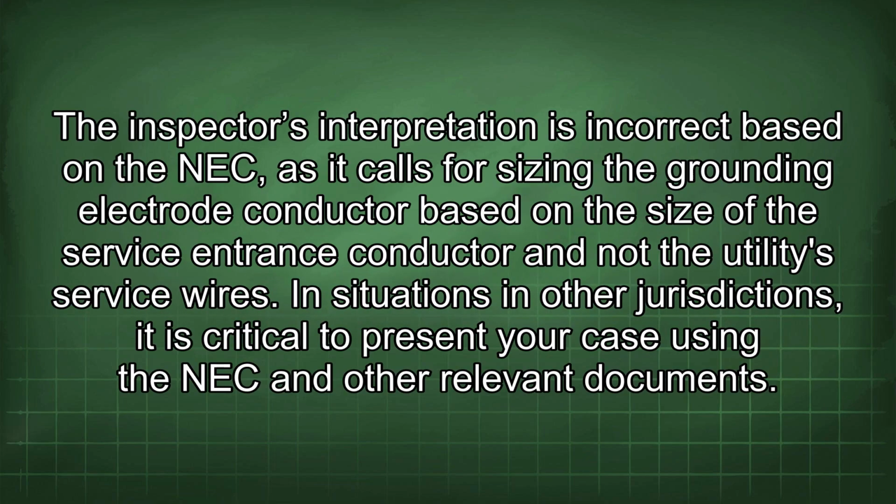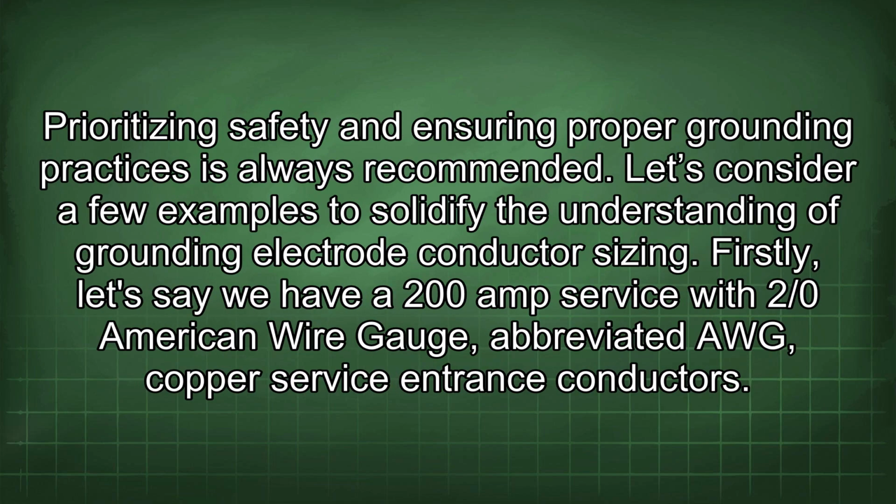The inspector's interpretation is incorrect based on the NEC, as it calls for sizing the grounding electrode conductor based on the size of the service entrance conductor and not the utility's service wires. In situations in other jurisdictions, it is critical to present your case using the NEC and other relevant documents. Prioritizing safety and ensuring proper grounding practices is always recommended. Let's consider a few examples to solidify the understanding of grounding electrode conductor sizing.